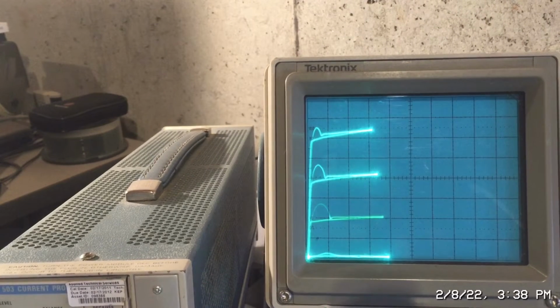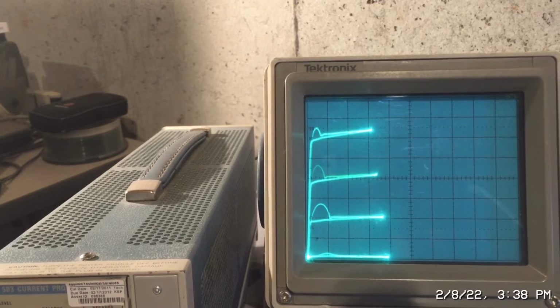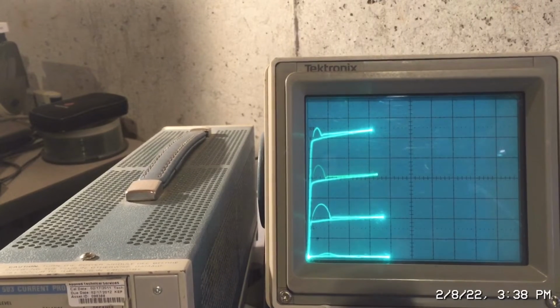Okay, so now I'm back. This time we're taking a look at the Toshiba 2SC2879. So that's what the collector characteristic curves look like. This particular component has a pretty high amount of input capacitance and output capacitance, so you see the looping effect there, which is pretty common. You can kind of compensate here. It's about as good as I can get it.